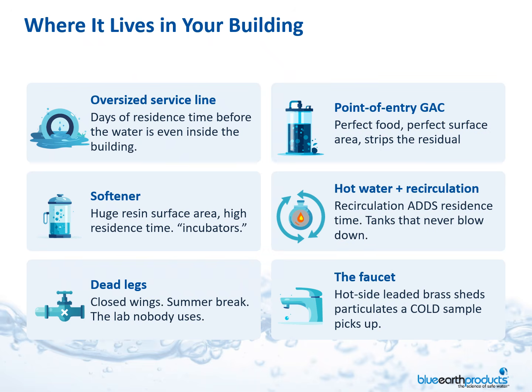Probably in other places today, you've heard about biofilm being in various places in the building, specifically with stagnant water or with large surface areas like the softener and the GAC, or in the hot water system. So these are good places to look if you're looking for it.